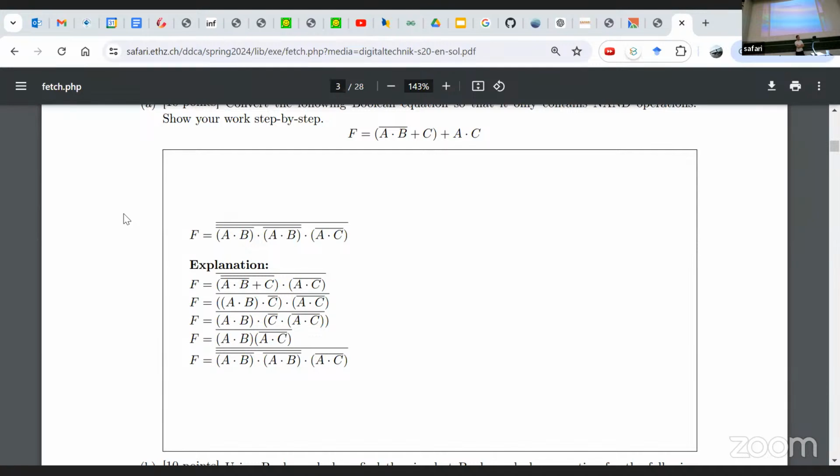The problematic part is, once we start pipelining it, once we use different clock cycles to do these operations, while I'm decoding it, while I'm fetching, while I'm getting the operands, it may not already be written back. So this is when we start having hazards. But in a single cycle architecture, which is nice, you don't have these issues. Everything completes. The entirety of the operation is done, which is great. So there's no race whatsoever.